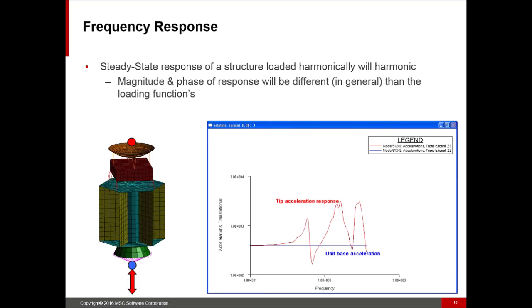In the previous plots, I won't go back to it, but we talked about the dB per hertz. Your microphone, accelerometers, however you're getting that type of data, may of course go up into a much higher frequency range. That's great, but from a practical standpoint, when we do a frequency response analysis on a structure, part of what we're also getting, just looking at it without any idea what the load is, is that at the higher frequencies there's no real response. It just follows whatever the excitation is. So we do usually have a pretty good idea of what that range is.